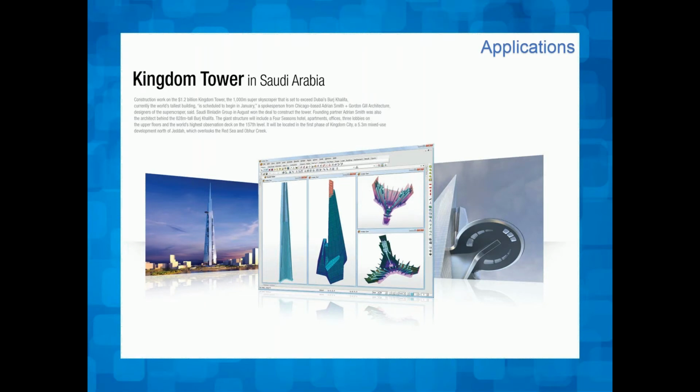The reason is it has a really easy interface and makes modeling extremely easy, thus saving time tremendously. Secondly, it has a powerful 64-bit solver which enhances the speed and is comparatively quick. The third thing is that it is specialized software for column shortening, which is very important for high-rise structures. And lastly, it has a tight integration with MIDAS GTS NX, which is an expert 3D software for piled raft foundation. Kingdom Tower has a piled raft foundation, and thus they needed GTS NX as well.